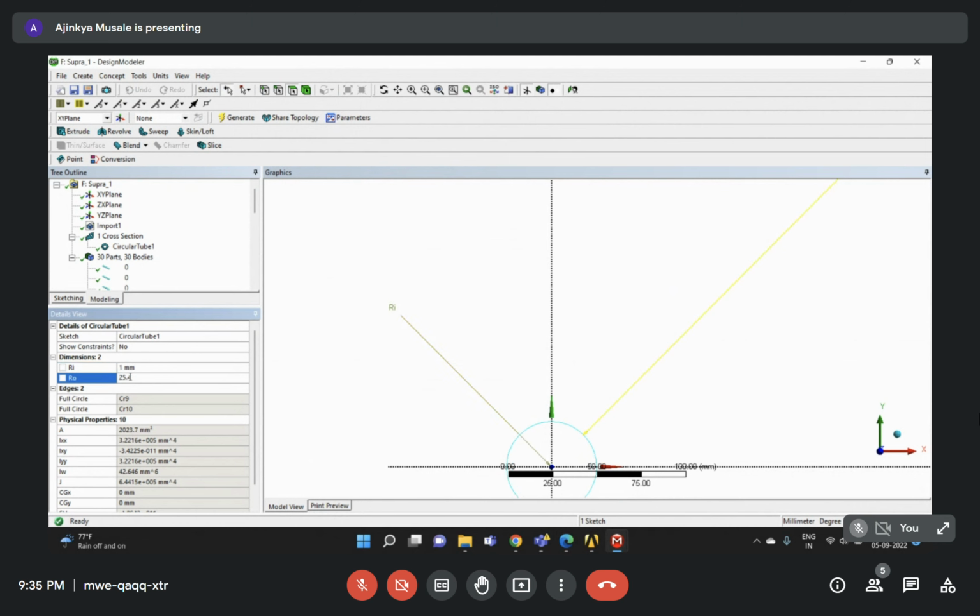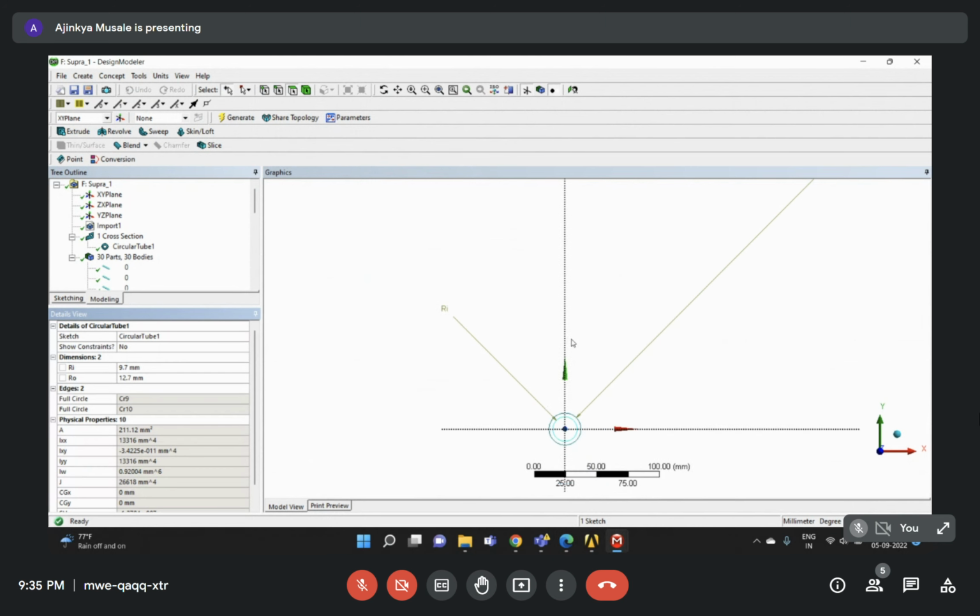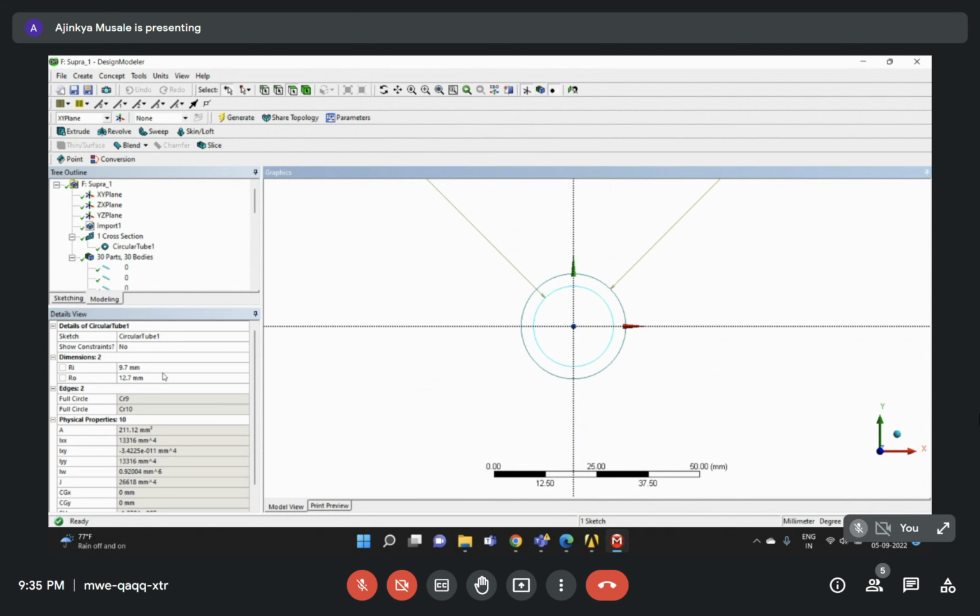So I simply make it, just go to the end and set 2. Now it has defined 12.7 for me. And now just go over here, say 12.7 minus 3 millimeters. So you can do that algebraic calculation directly here by putting the is equal to sign.